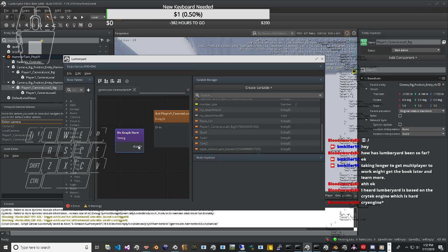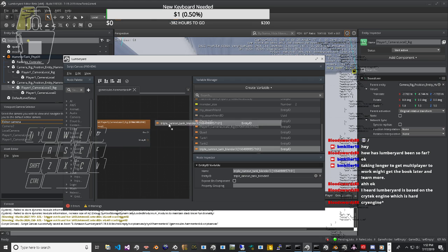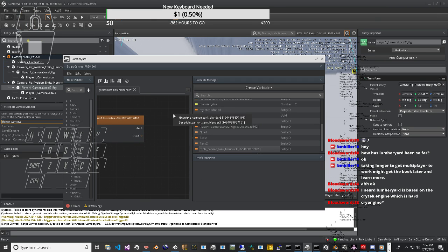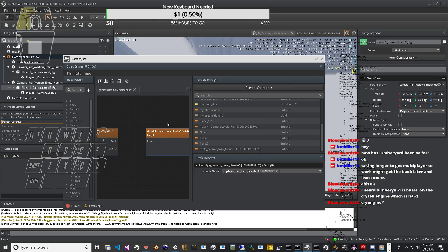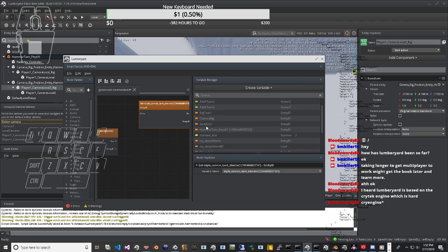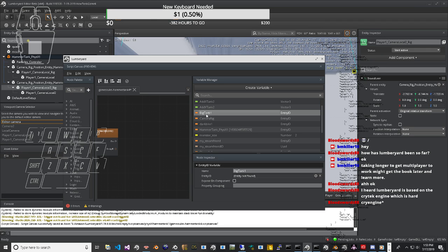The next coordinate frame is path. The velocity vector of the car traces out a curve in three-dimensional space such that it is tangent to the curve at every instant. The x direction of path points along the velocity vector. The z direction of path is at right angles to the x direction and in the plane formed by the velocity vector and the z direction of Earth. The y direction of path completes the frame such that x, y, z form an orthogonal, right-handed triad. The path of the car lies instantaneously in the xy plane of path.